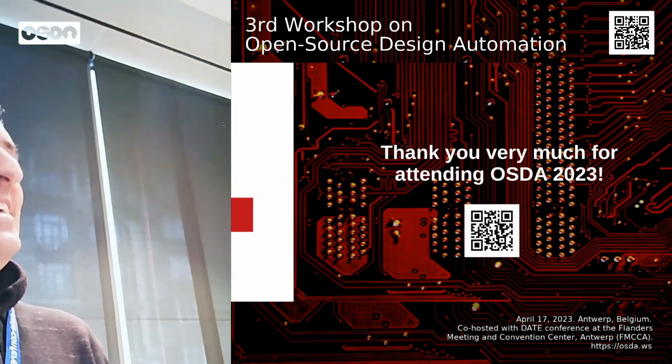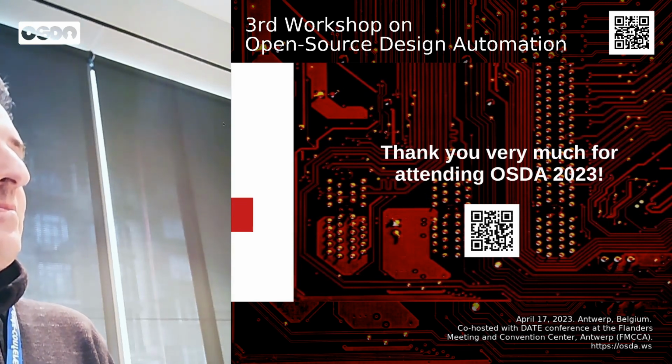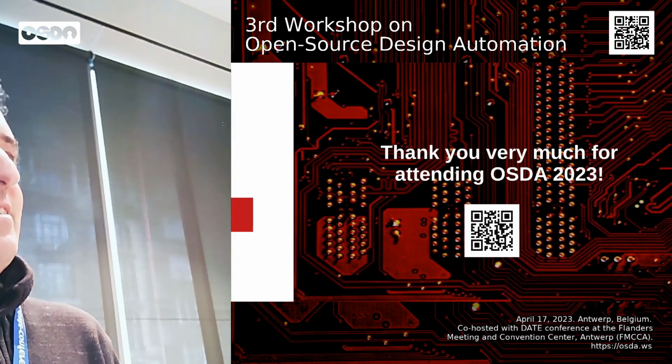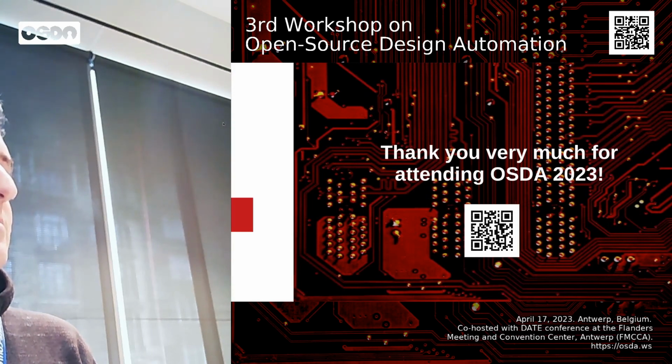I mean, somebody says, I'm going to open source this bench, or I'm going to develop this vertical benchmark. I'm going to provide a test bench for this so we can do calibrated power calculation and dynamic power calculation, vectorless, vector. I mean, there's so much stuff. SI, CCS, I mean, in the ASIC world, of course.